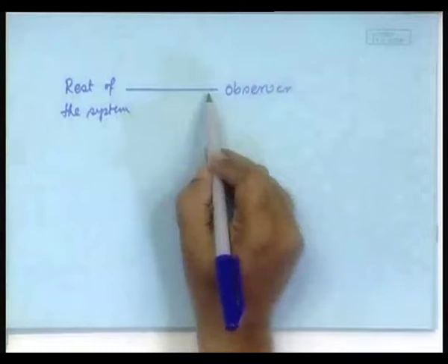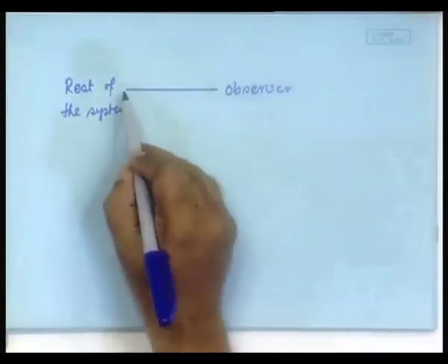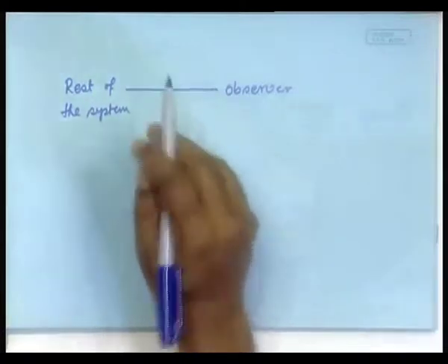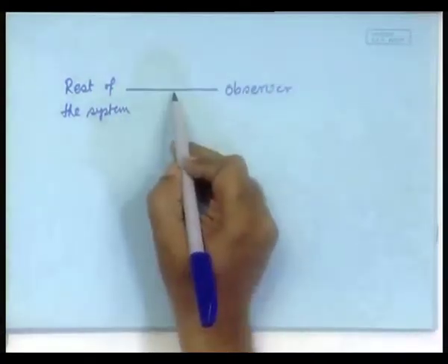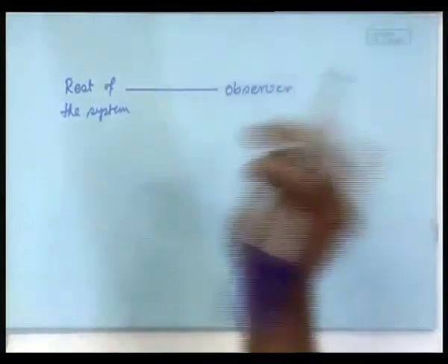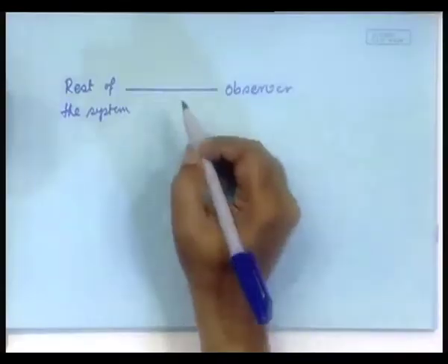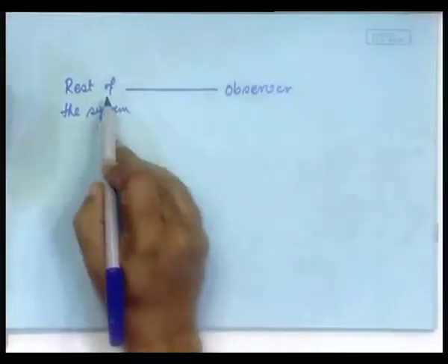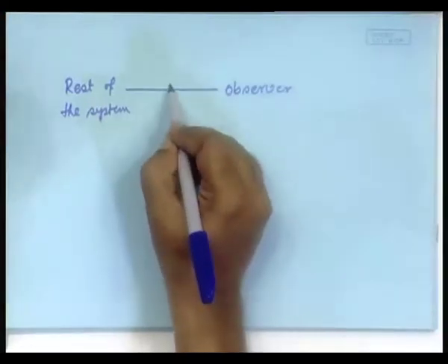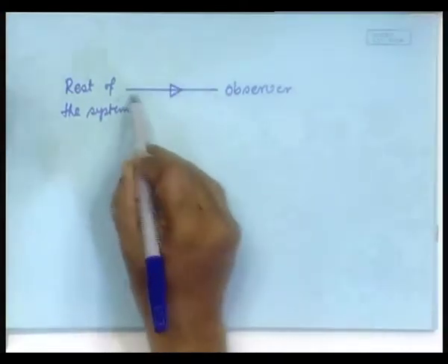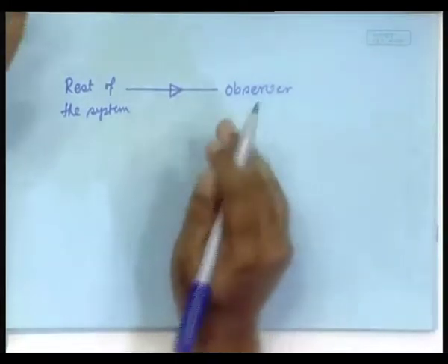It will not observe both in the same place. So, if it observes the flow, the effort is 0, then only it carries no power. If it observes the effort, the flow is 0, then only it carries no power, which means that for an observing element, one of the variables has to be masked, it has to be 0. Now, whenever we have this kind of a situation where we are sensing it, there we put a full arrow, meaning that this particular bond will carry no power.